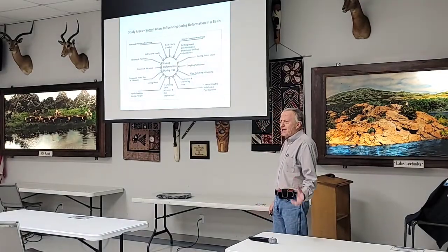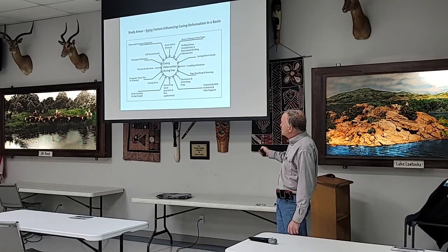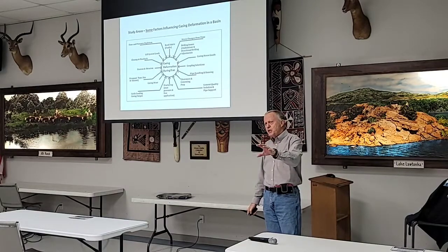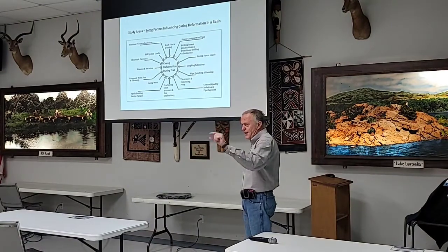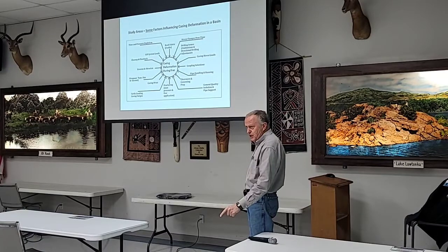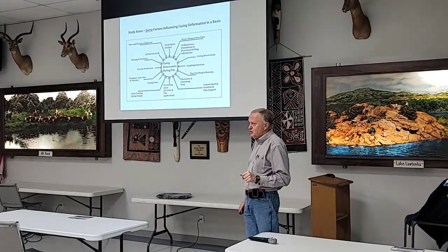Now, this is just a spider diagram looking at some of the fractures here, and casing deformation starts with, we look at the rock fabric, look at stresses over time, come around here, you look at a lot of these things. Coupling is mostly an API 8 round. About 50% of the wells we do is still API 8 round or modified buttress. If you have a gap in there, that first 40 or 50 joints down, and particularly right under the wellhead, you may see some severe